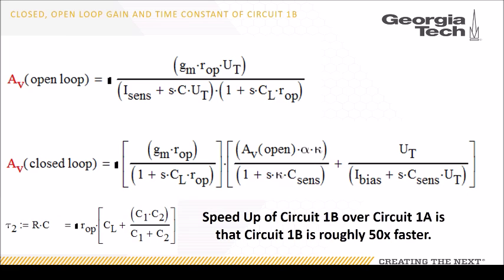Here you have the gain of the open loop of the feedback amplifier, and then you also have the closed loop of the feedback amplifier with this source follower stage feedback being included in there. The open loop gain is being multiplied in there because the open loop gain is in units of resistance, which is what is needed for the calculation to make sense dimensional analysis wise.